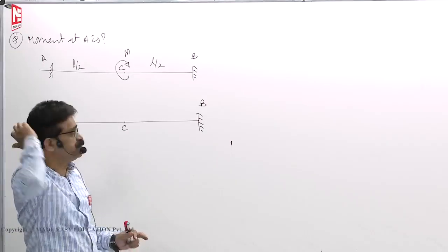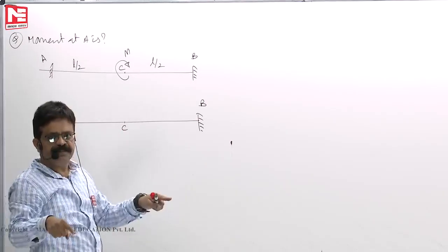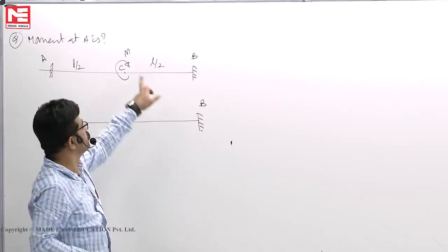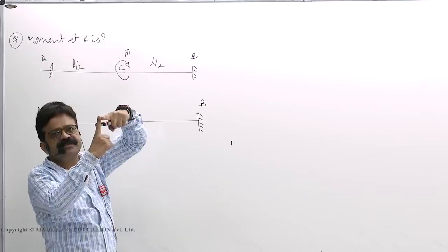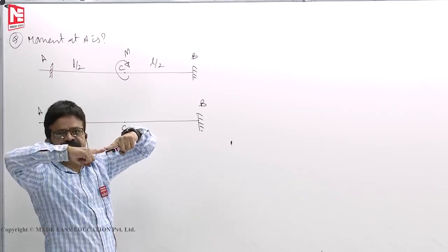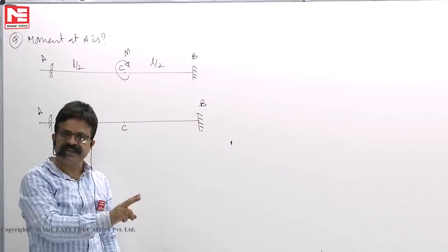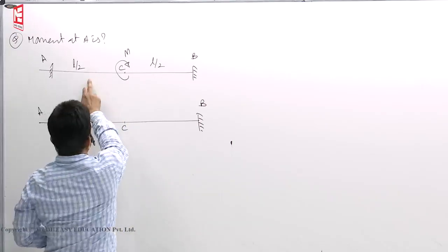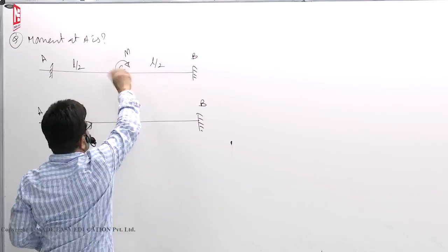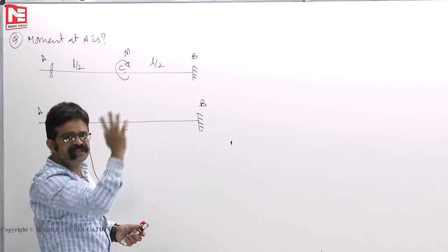Okay. Now instead of 90-degree bend, you have 180-degree bend, you assume. CA is one member, CB is another member. Instead of connecting like this, they are connected like that. Still, your moment will be shared by the two members equally, because L by 2, L by 2, same I. That means whatever moment you apply M, both will share equally.